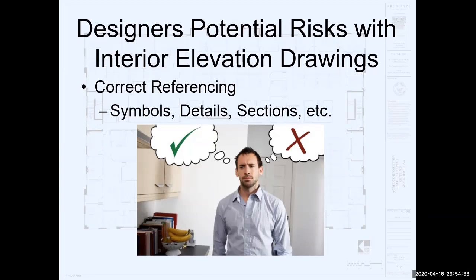Last week, I think we gave you some of that information, and it's intended to provide the symbol for identifying elevations inside the building. We don't rely on north, south, east, and west on an interior elevation because it gets kind of backwards. The north wall is actually facing south and people start getting a little confused with, is it a north elevation or is it a south elevation? So as a result, we use those industry standard symbols, and we'll see those a bit later here.